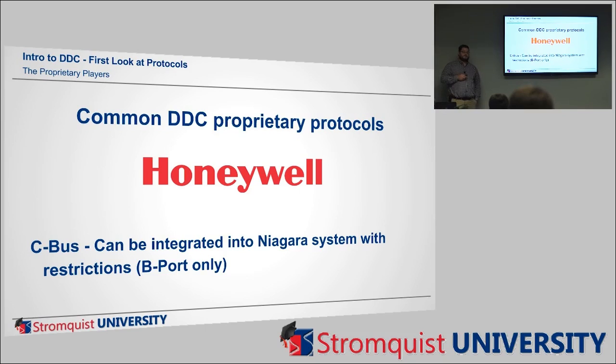You can get drivers for PLCs. That's one nice thing about the framework that Tritium developed with Niagara: other companies can write drivers for other stuff. So Johnson Controls, when they came out with their Jace, they actually have their own N2 driver that they wrote. Now, some other companies wrote N2 drivers to be able to put them on other Jaces because Johnson said, "If you want our N2 driver, you have to buy our Jace." There's third-party drivers out there, so you can pull into other Jaces.